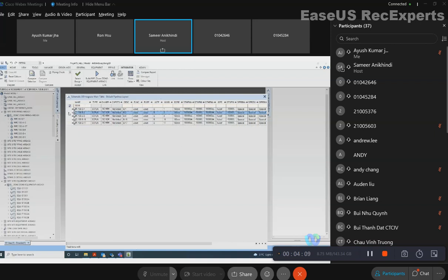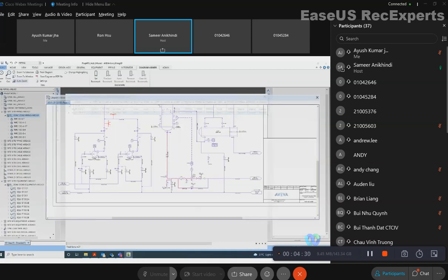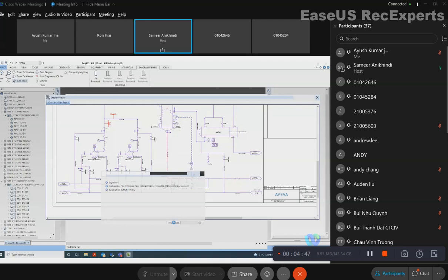Okay, 100-b-2. Either you can build it from here because you have already set this as build zone, set the build zone as piping area 01, and you can build it from here, or you can also view on diagram. So it will open the diagram on which this line is there, and you can right click on the label of the pipe and you can click this build pipe. So see, it says 175 elements, some log is reporting here.